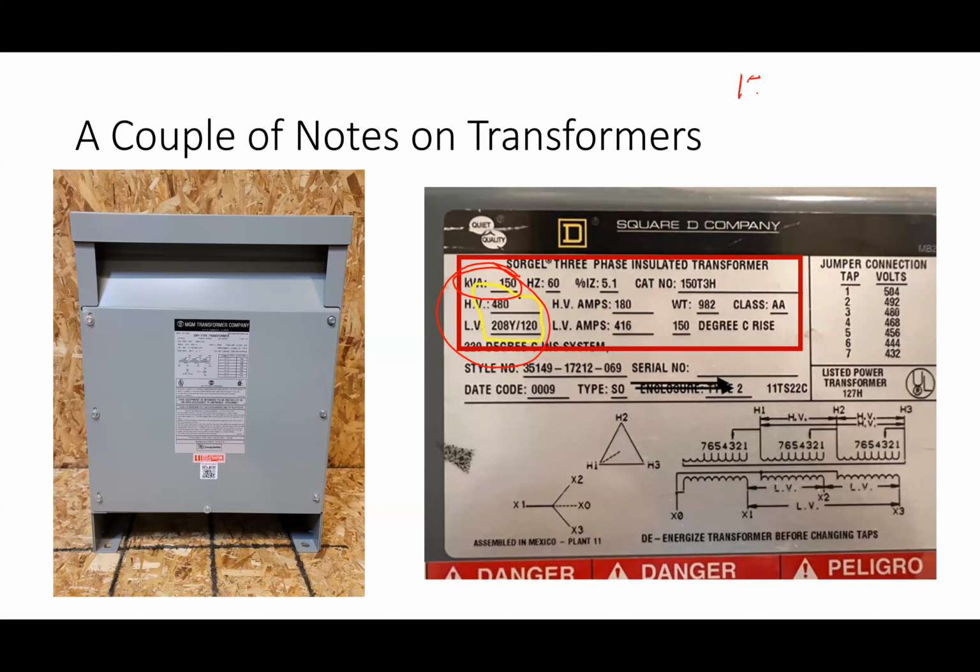So 150 kVA. In our little power triangle here, who's that? What units is kVA? It's apparent power, right? This basically means that's the maximum S, the magnitude of S. S is a vector; magnitude of S is a number. That's a pretty typical way to rate stuff, because what it tells me directly is, if I'm putting in 480 volts, 150 kVA, I can get directly to the maximum current that I can ever pass through this thing. Where does that number come from?